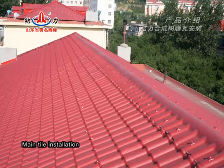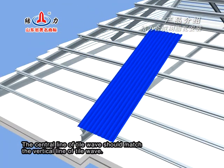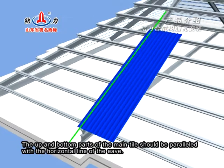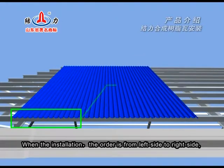Main tile installation. Main tile installation on two slopes roof. The installation should be started from the edge of the roof. The central line of tile wave should match the vertical line of tile wave. The up and bottom parts of the main tile should be parallel with the horizontal line of the eave. When installing, the order is from left side to right side.